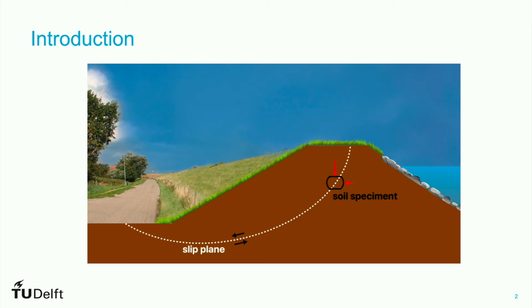Here you see an example of the engineering application of the test. The dike loads the soil, which provides strength, but the weight of the soil also creates an overturning moment which acts to fail the dike along the slip plane shown. When the critical strength of a soil is reached, a failure mechanism can occur that leads to a slip surface. The Triaxial test provides strength information of a soil under specific confining pressures, for example like the specimen shown here at the top of a dike.